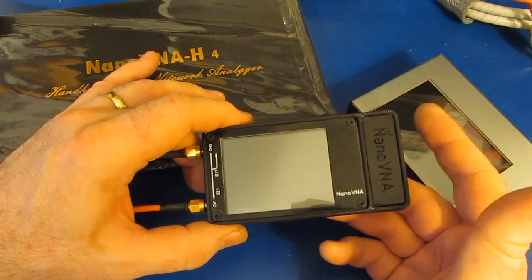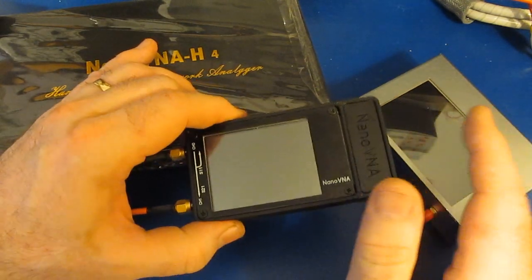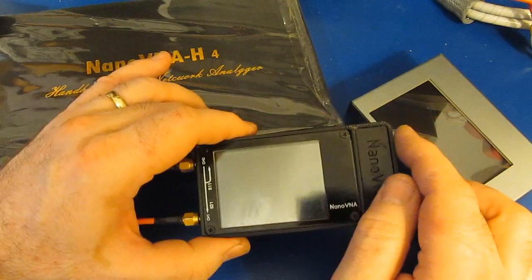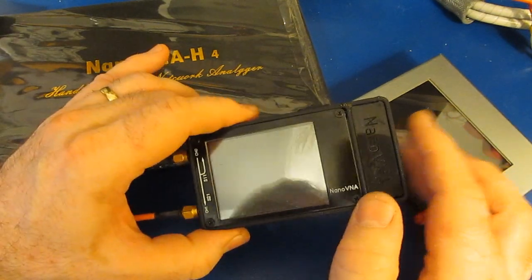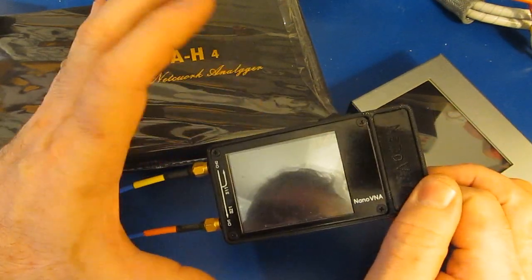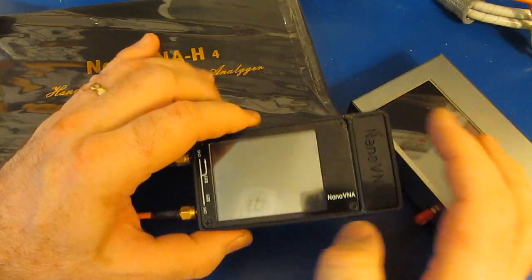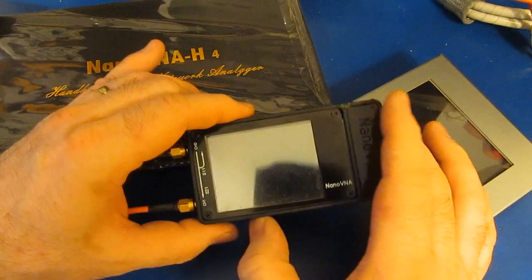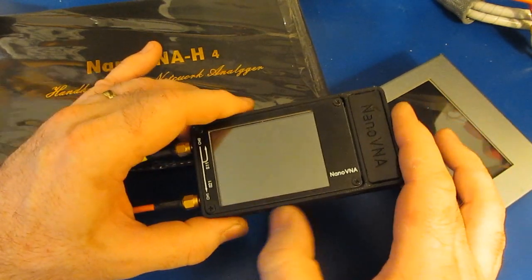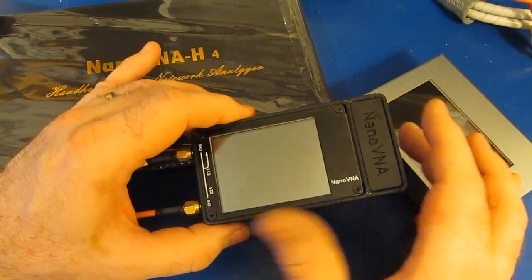So in order to measure a PDN, we'll need a network analyzer that can operate at very low frequencies. You may wonder, if we're talking about high-speed digital designs, why do I care about low frequencies? Typically your power supply is going to be located on the same circuit board with your logic, and the loop response of those power supplies is going to be very slow. So what we'd like is a network analyzer that can make measurements well below a megahertz.